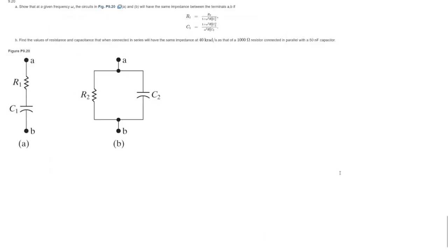So this problem is going to be similar to the last one. We've got equivalent impedance with a capacitor instead of an inductor this time. So ZA is going to be the resistance in series with the impedance of the capacitor. So it's going to be 1 over J omega C1. And ZB is going to be...